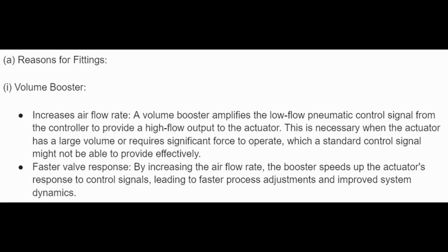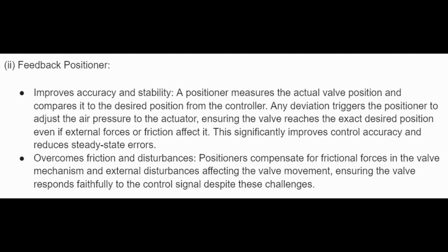Faster valve response. By increasing the airflow rate, the booster speeds up the actuator's response to control signals, leading to faster process adjustment and improved system dynamics.